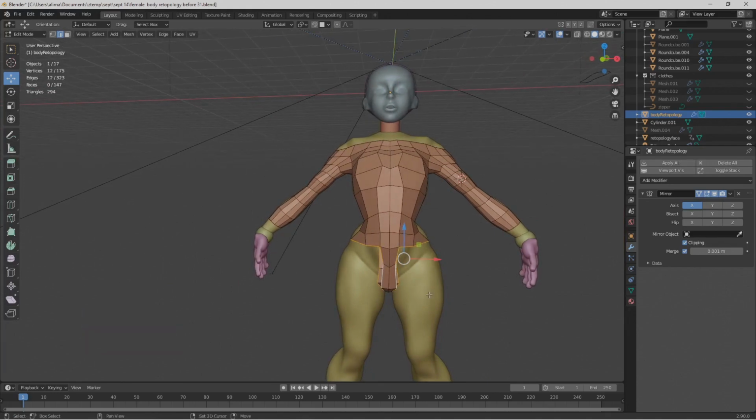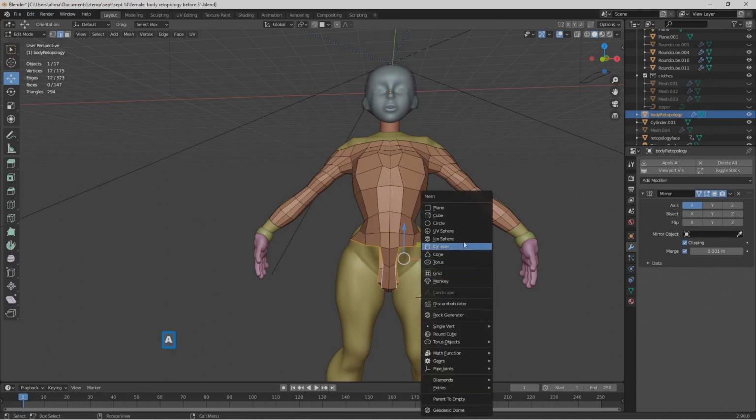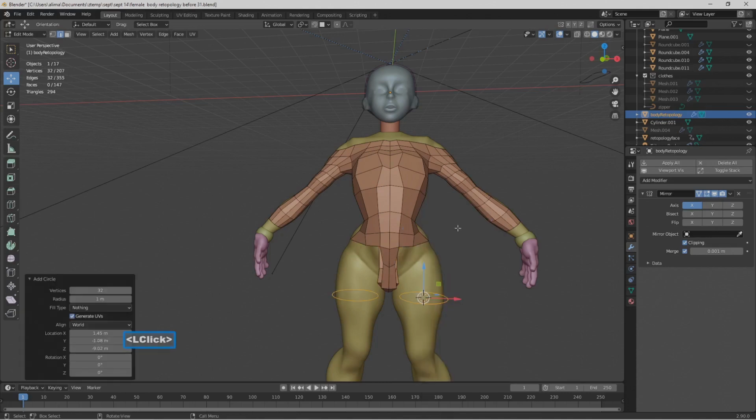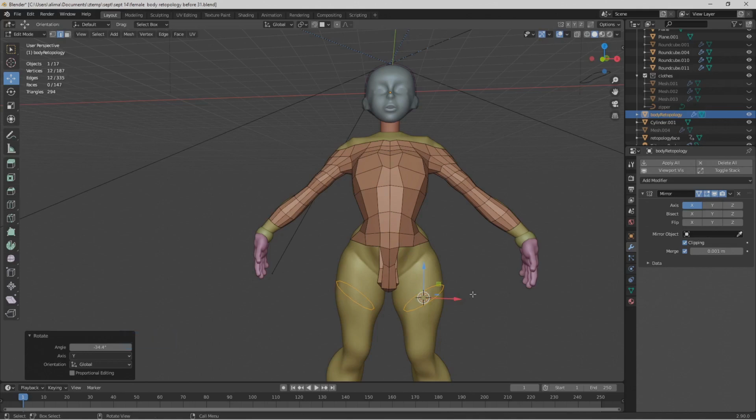Well, what we're going to do now is hold Shift, press R. We did that to put the 3D cursor there. We'll hold Shift, press A. We'll bring in a mesh circle. We'll change this to be 12. That 12 should match up with this here. We'll press R to rotate on the Y axis like this. We'll press S to make this bigger.